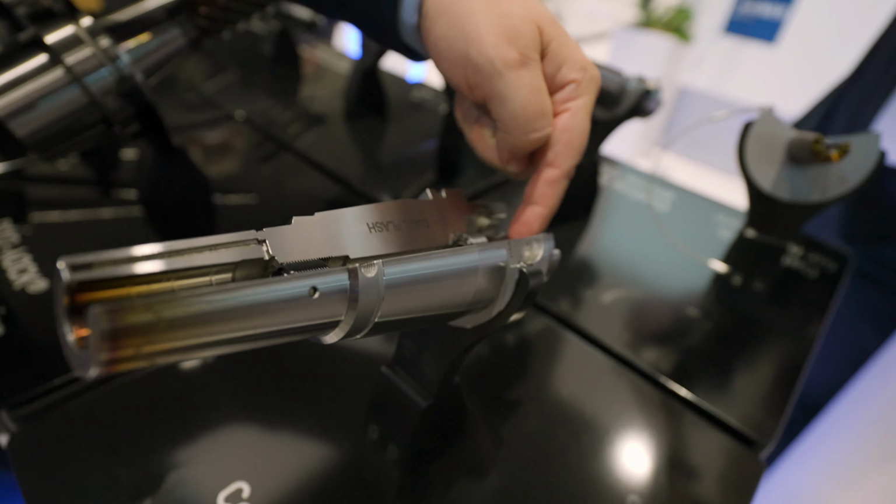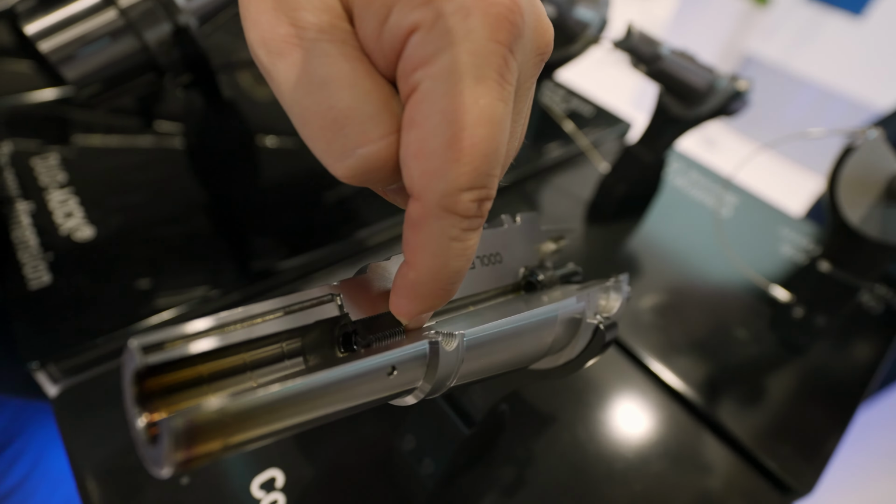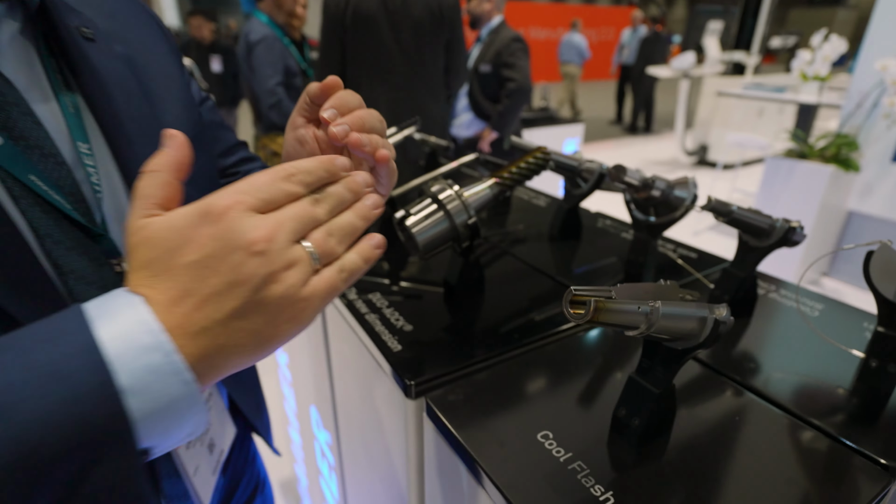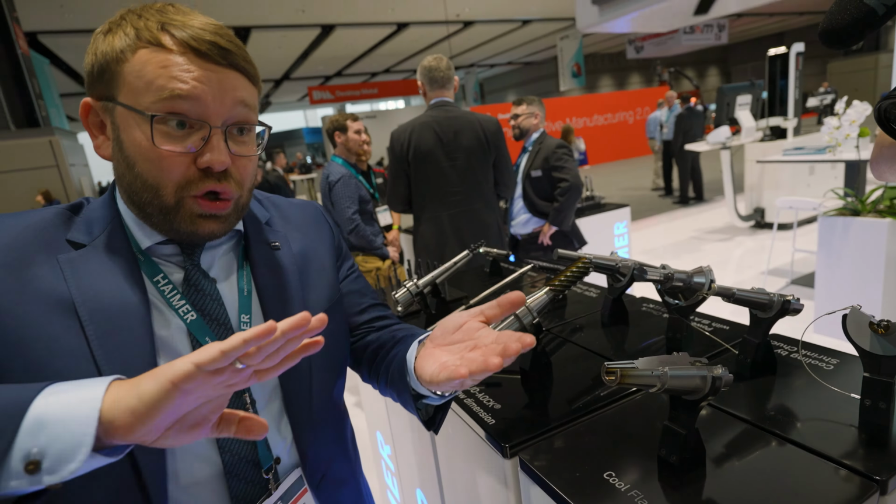So here you see the coolant comes from internal coolant, comes here, then it goes to these channels here, and there is a pressure chamber on top of it. So it's like a garden hose effect. We create more pressure and the coolant accelerates faster, so it goes in the flutes. So if you film inside here, you can see actually the coolant go in the flute of the cutting edge for maximum chip evacuation. That right there is amazing.